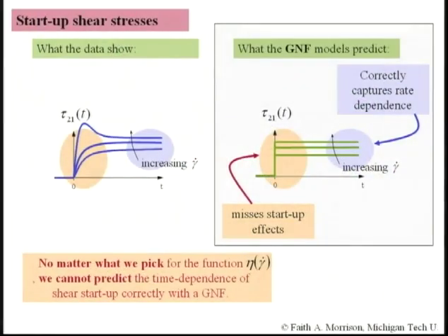So this slide emphasizes this. The generalized Newtonian models can capture this change in ultimate stress. That's okay. That's the shear thinning part of the viscosity function, is determining what these constant stresses are, and it does that part. It cannot do this part.